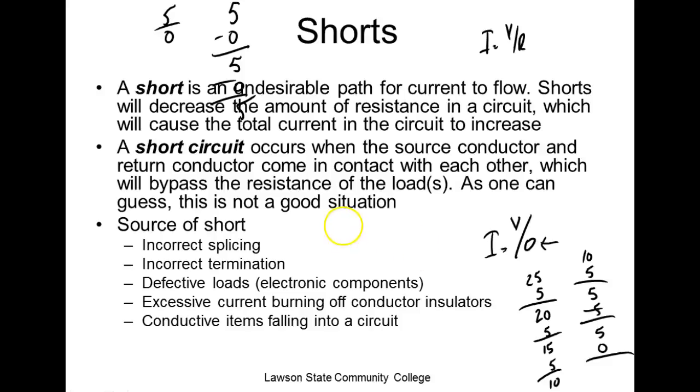which means I come over here, normally we have our voltage source, and then I go over here to a resistor. Well, a short circuit means I connect there to there. And what did I lose? I lose the R of the load. So now it says, okay, if those wires had 0 resistance, I'm taking V divided by 0, and my current would go to infinity.